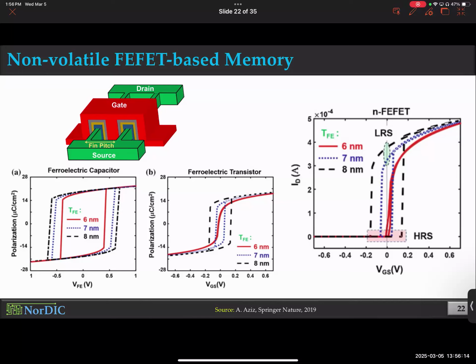Okay, but getting back to the conventional structure of a ferroelectric FET-based transistor, have we seen this before in NC-FET? Didn't we? So basically, you have the exact same structure. What changes is the thickness of the ferroelectric. Apparently, by tuning the thickness, you can harness the negative capacitance nature or just the conventional FEFET nature. So the structure of the transistor doesn't change at all. The only thing that changes is typically the thickness of the ferroelectric. Are you guys all good with that?